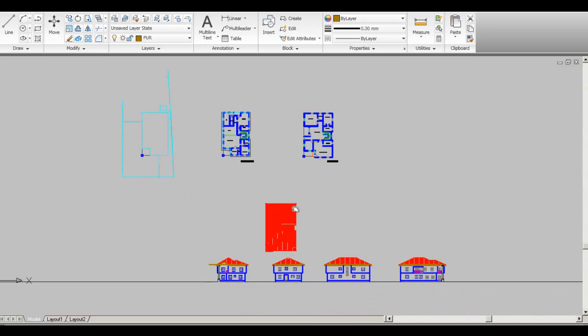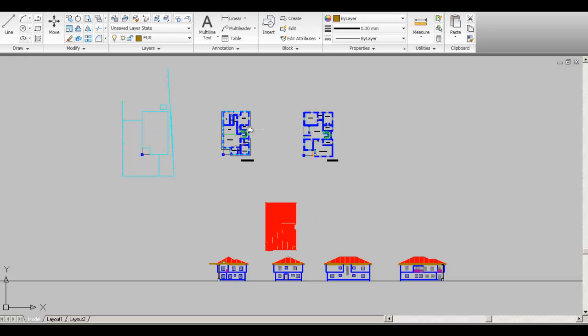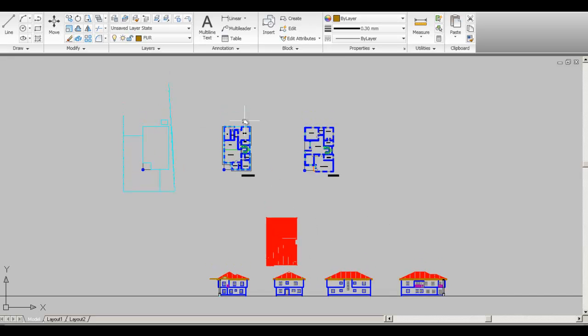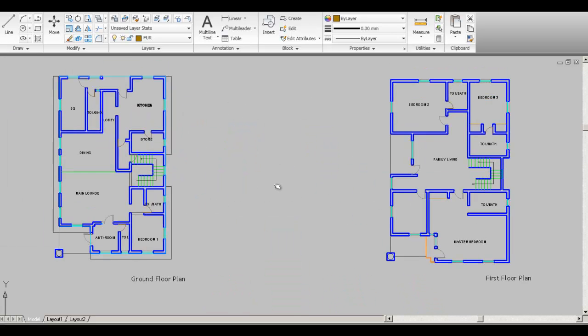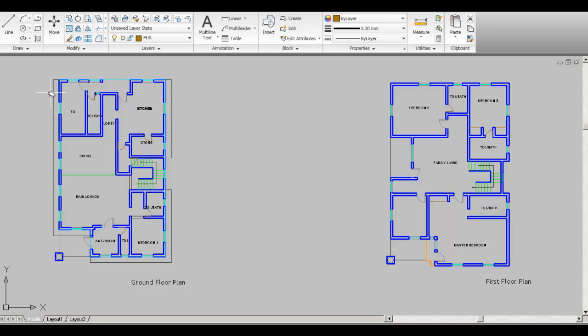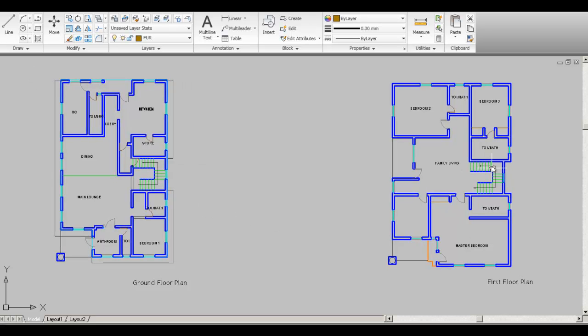What I now do is I prepare my model from my 2D drawings for export into 3ds Max. So I just pick up the plan, I clean it up, I get rid of the text, the unnecessary lines, unnecessary layers that I don't need. Like, I don't need the stairs looking like this. Well, maybe I might need the stairs, at least if I have to create the interior space. So all I need is the walls, the windows, the doors, and the stair area.